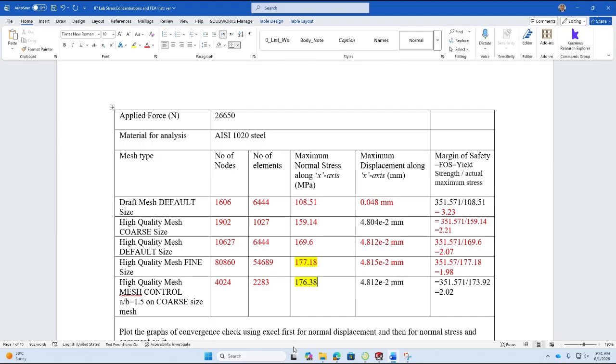And sir, for the project, can we use just the first and last one only, or do I have to do it? I mean, you can, as long as you show me that you have that sense of having a converged mesh, that's fine. You can use the first and last maybe, and discuss it. I don't want you to do a full convergence study. In real analysis, you will always do one, because you'll have bigger parts, so you may do the full convergence study for one smaller part and then leave it for the rest. But in your case, it's okay. You can just use the first and the last. You can see here that now the factor of safety has almost converged.